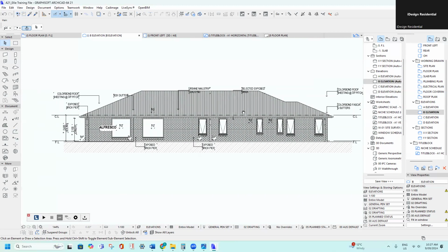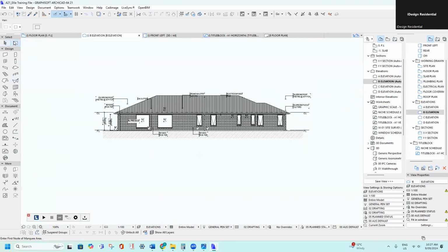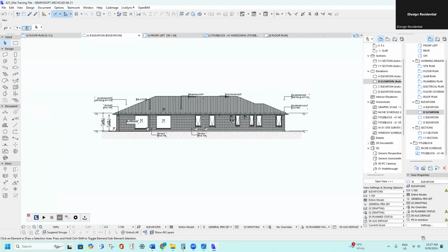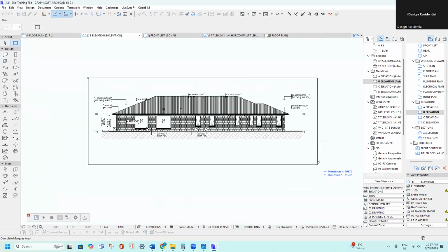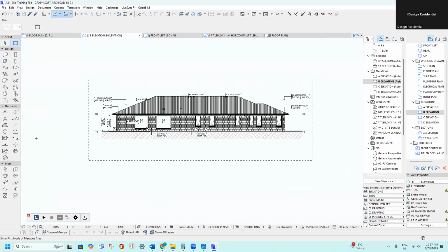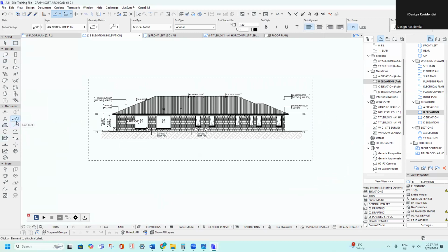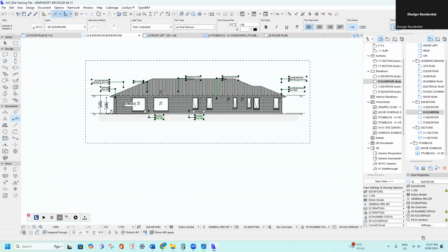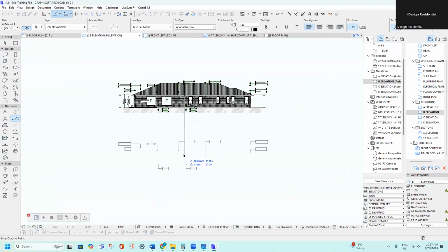So sometimes if you're using the same notes over and over again, like in this particular one here, you could click on the marquee, hover over all of the elevation, click the elevation label, press Control A to highlight all of the arrow notes, and press Control D, and you can drag them all away.